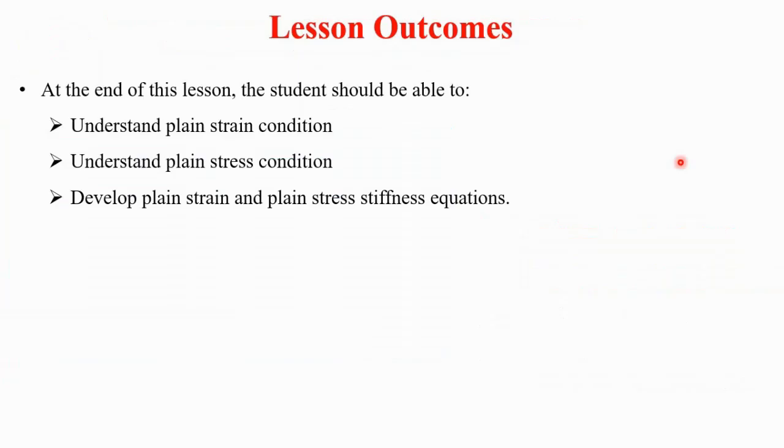Today we are going to discuss plane stresses and plane strains in finite element analysis. First of all, we will discuss the lesson outcomes. At the end of this lesson, the student should be able to understand plane stress, what is meant by plane stress, and what the conditions for plane stress are. Then the student should be able to understand the plane strain conditions. Then the student should be able to develop the plane stress and plane strain stiffness equations, or again, we can say the plane stress and plane strain matrices.